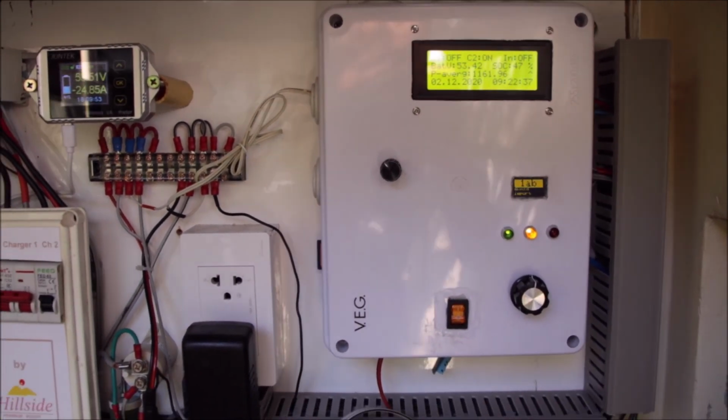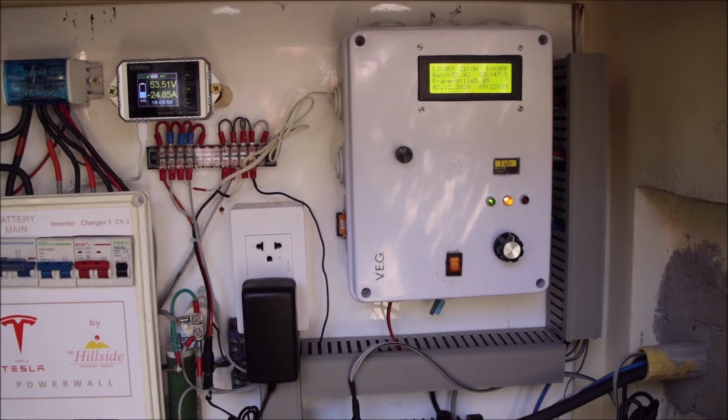Just go back to the main building and give it a final thought. The CT of the SUN inverter is changed to one with a bigger opening, so I could use it on bigger diameter cables to measure my current. It works as expected. We have now the opportunity to also push energy into 3 more buildings, not only our owner's apartments, so we can really cycle the full capacity of the battery on probably a daily basis, or at least when there are guests in the hotel.